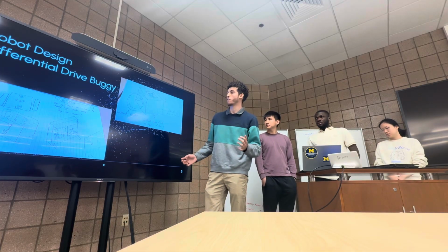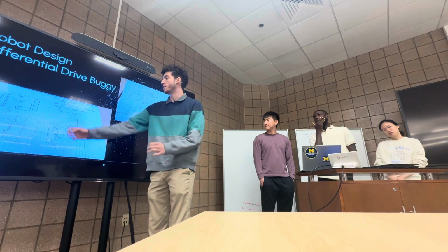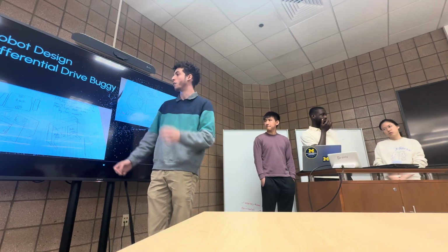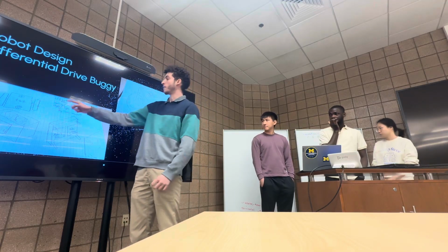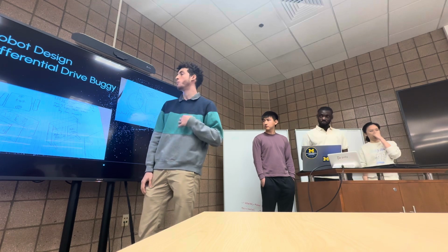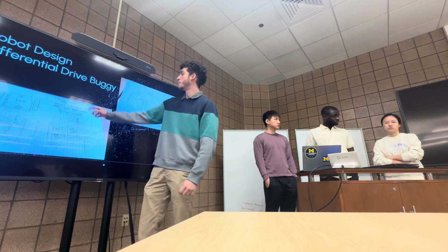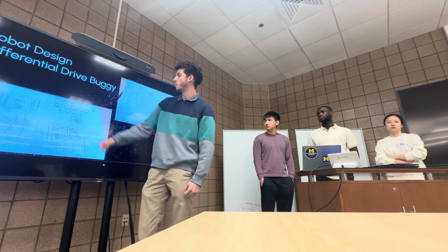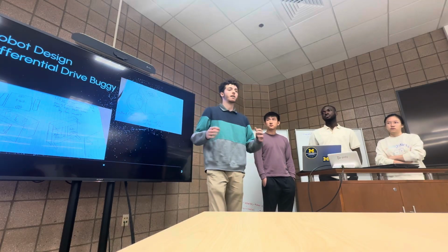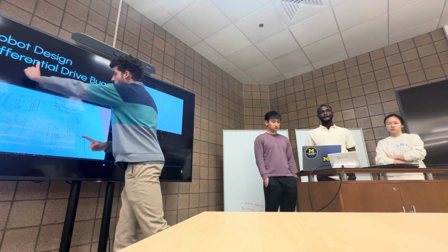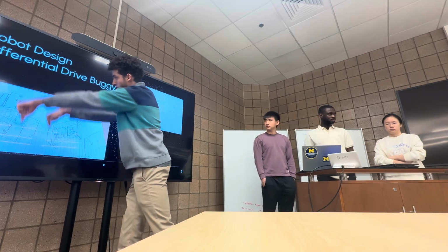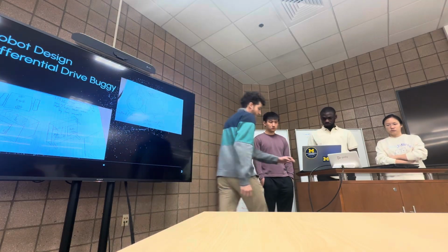Because there's always 3 points of contact, we want to make sure that there's an extra point so that we're not flopping all over. So we're going to either use some ball bearings, or if we can keep within the material restrictions, just some low friction material that's slightly above where the wheels come down to. The idea being that when you're accelerating forward, in this direction, this point will hit. If you're accelerating in this direction, this point will hit.